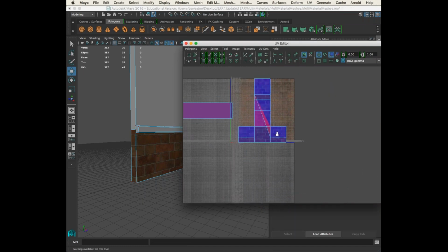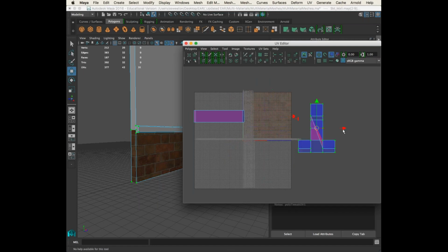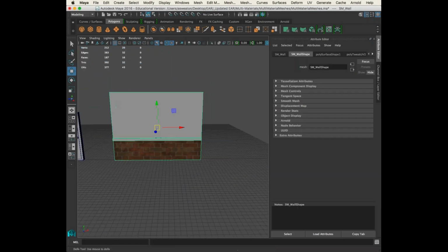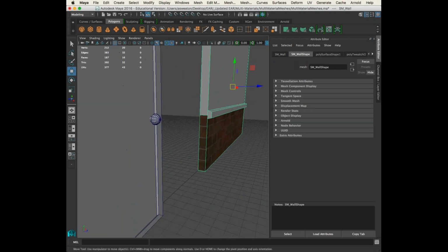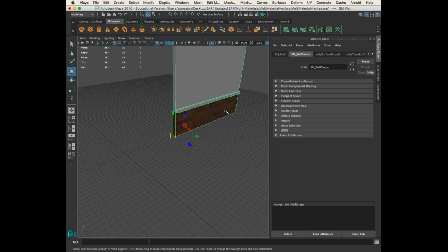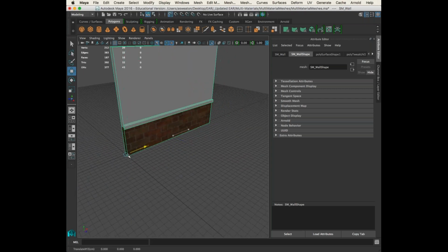All right, and for these UVs, again, you guys can take the time to UV them. Hopefully they already have some sort of UV done to them. They're not left at default, so you can just group them, and usually I just shrink them down and put them somewhere else because I don't want them to be in my way. So when it comes to this section of it, the main thing that you want to look for is if your material is tiling. Now I'm going to put my pivot, hopefully again all of your pivots are correct. So let me actually put this at the origin. I'm going to turn my grid snapping on. So what I like to do is I like to go ahead and just duplicate one of these on both ends.